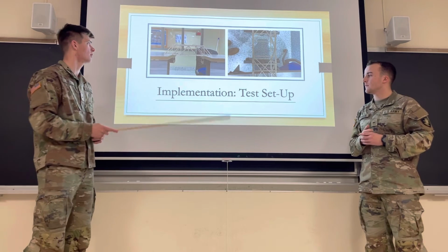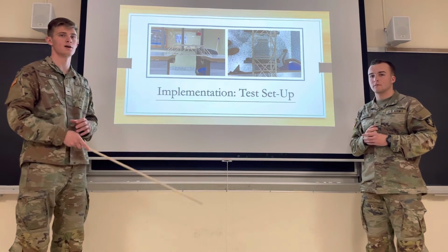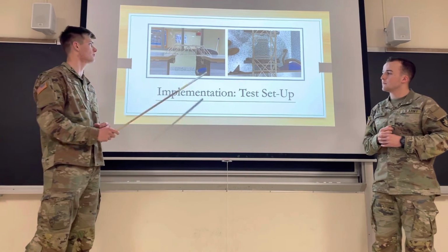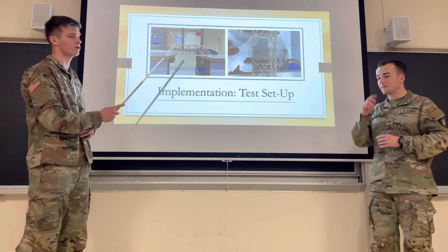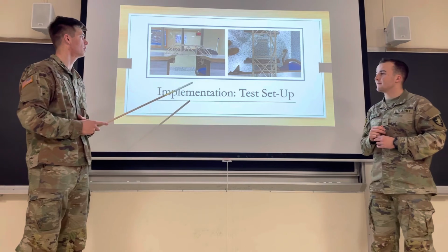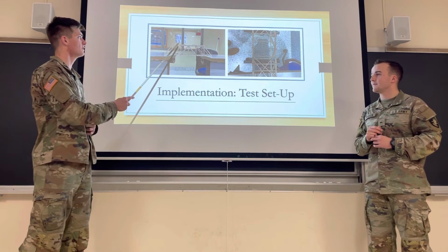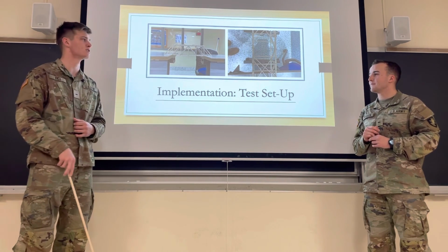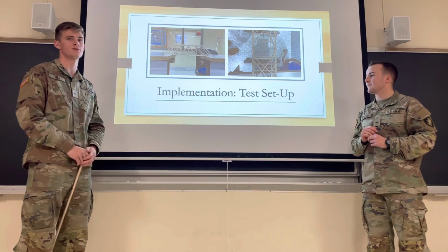And then also, while we were building it, we found that our designs weren't exactly foolproof and were more difficult to build than expected, so we left a little wiggle room for the scraper to fit inside. We made it 110 millimeters in height instead of 100. And then we also made these beams on the side, which were in tension. We put 2 on each side to finish out.